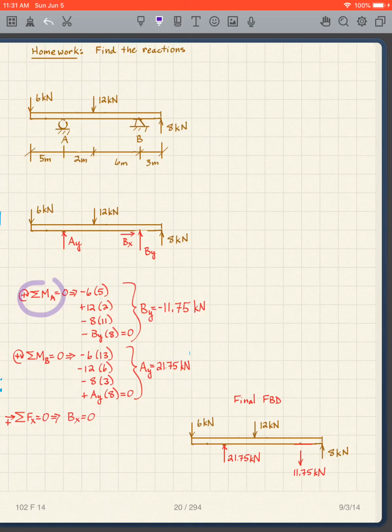And I'm going to take moments about A. So here's A. So it's going to be 6 times 5, 12 times 2, BY times 8, 8 times 11, and then what are the signs?